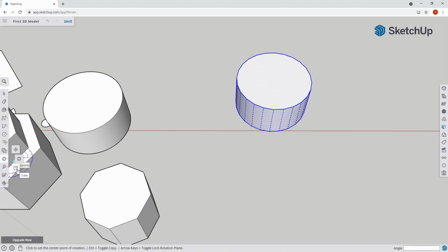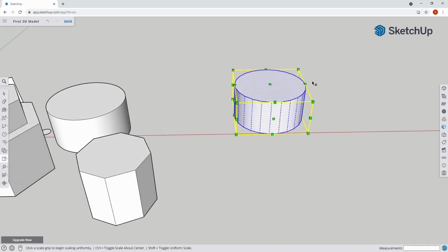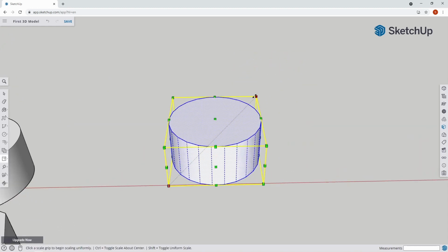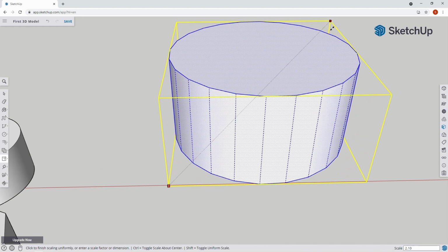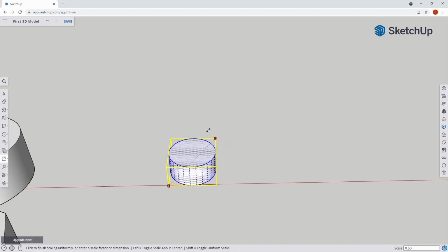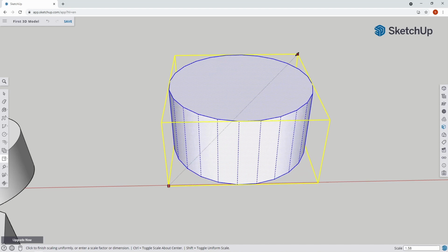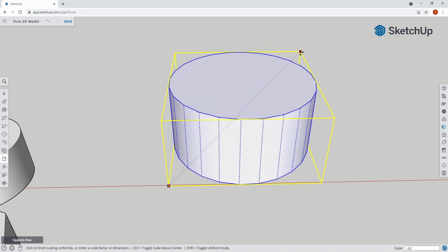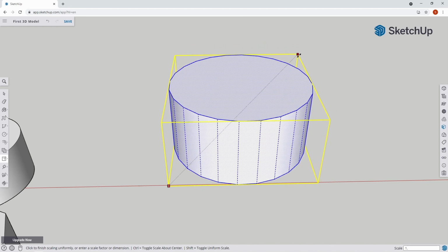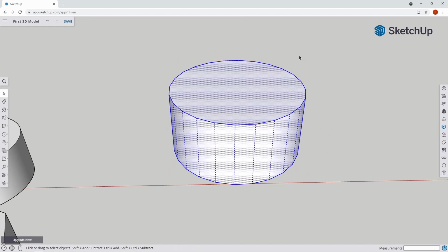And then finally, the scale tool. So the scale tool allows me to scale an object. So this one takes it, and if I choose the corner, it'll manipulate all three of the dimensions all at once. So you can see it's scaling in the bottom right hand corner. That's 50, and that's 100% or its exact scale, 150, etc. So let's make it 1.5. Enter. And there we go. So if this was originally, let's say, 20, this would now be 30. So it's scaled up 150%. And so that's basically going to cover that tool.